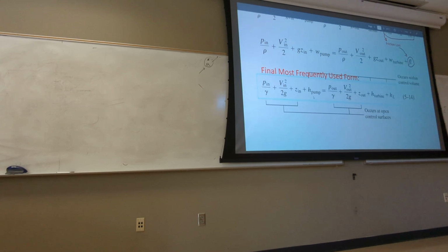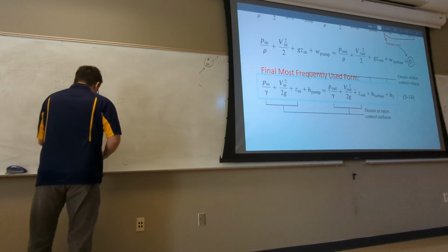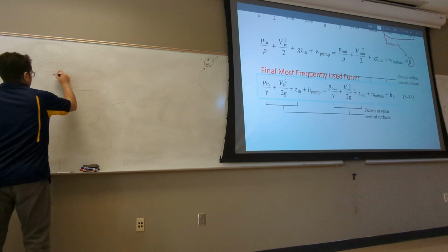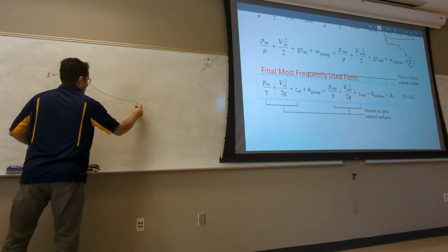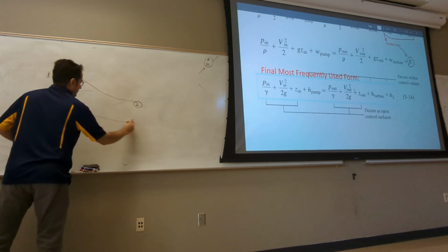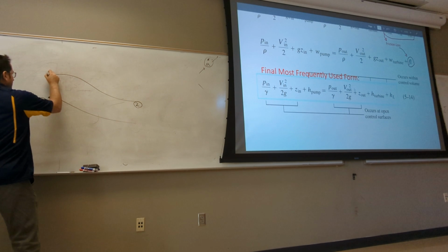But look, if you make this assumption, there is no heat loss, there is no friction, there is no nothing like that, this Bernoulli is not only between these 2 points, but also between any point in the field. And you can immediately justify that by just considering this basic fact. You go from this point, let's say this will flow, 1, 2, right, 3, 4.